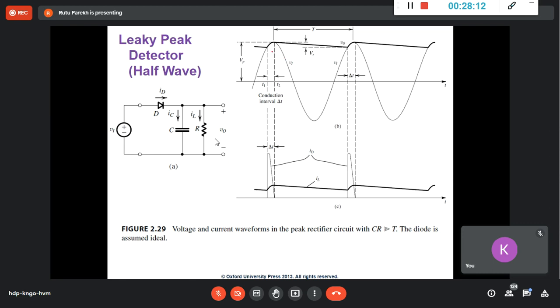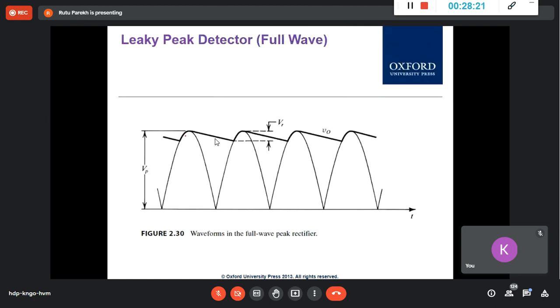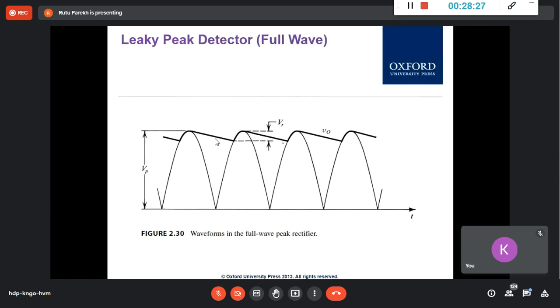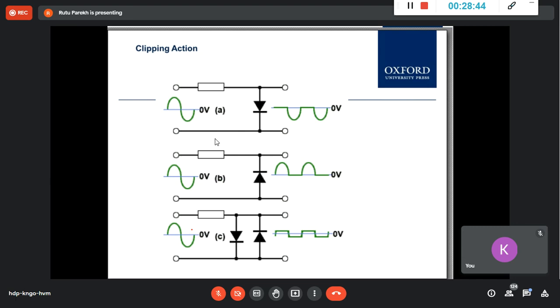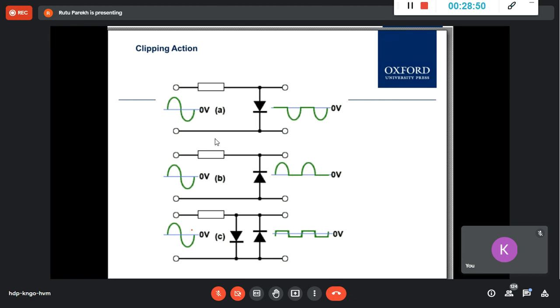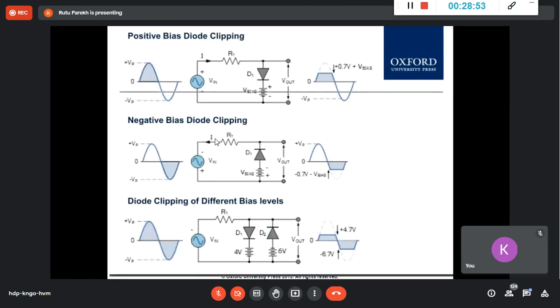And so this was for half wave, right? So this is a half wave rectifier. If you make a full wave, then for the negative half also you will have a positive cycle, and you will get it like this with this ripple. So this is your ripple, from this minimum to this maximum. This is your ripple voltage, and this dark line is your V0. This is for full wave, as you can understand. Then we use Zener diode to get pure DC, and we will see that also. But you have understood Zener, and I will touch on that also.